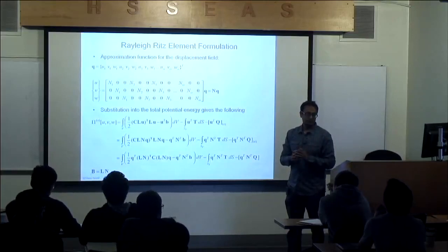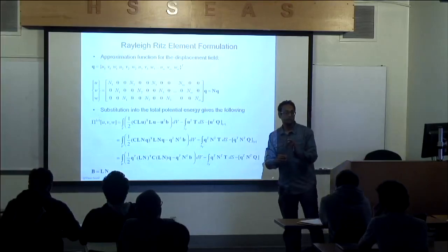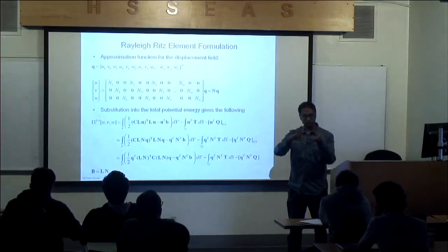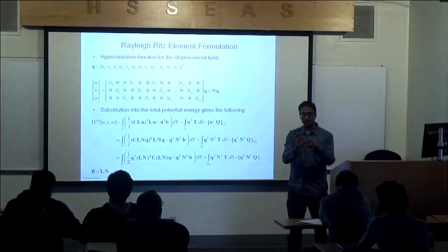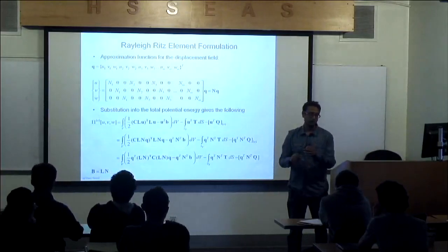So what does it mean that U is the sum of the individual U's of each node, as opposed to an average? We're not doing an average. We're interpolating the displacements inside that cube or hexahedral element, using the nodal values and the interpolation functions that go along with them.